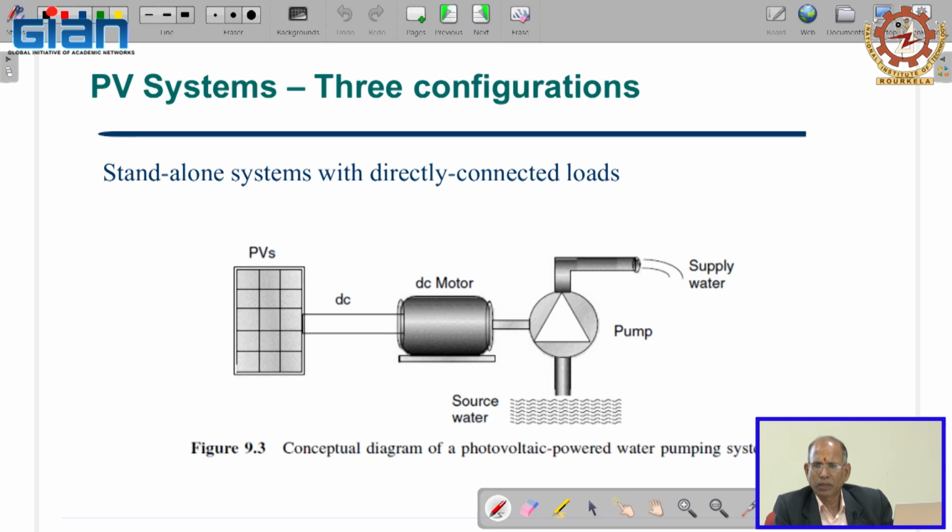So if we have tube wells, how are we going to extract the water from the ground? We can use this PV along with a DC motor. We do not want to use a battery, to keep the PV system low cost. Not even inverters. We want a simple system, very robust, low maintenance and least costly.